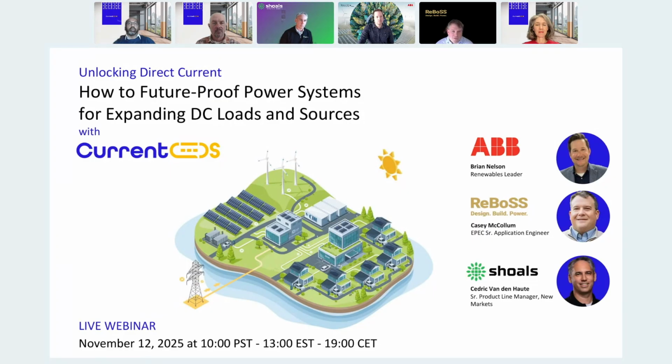Yeah, I think what Cédric mentioned before about historically, battery energy storage being an AC coupled application. I think definitely the move to DC coupling for renewables and battery energy storage, removing that first level of unnecessary power conversion as we're getting into a native DC bus for data centers and for other applications, is going to be the biggest change, with the rate of construction and implementation of both renewables and data centers.